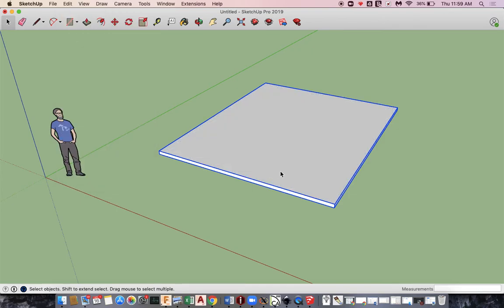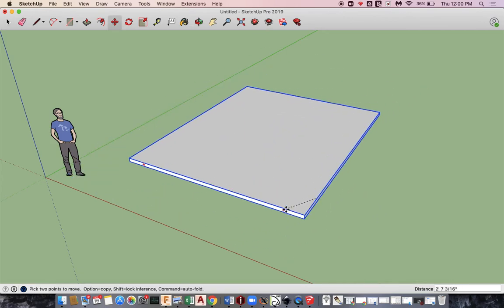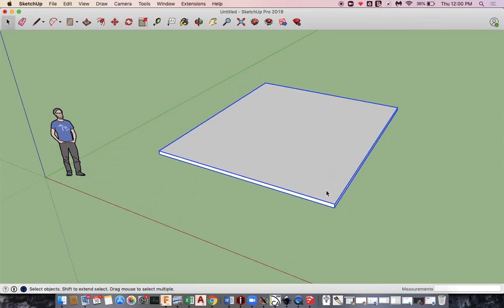Just hit Command G. Now, to tell that it's a group, it doesn't look any different when you're done, but when you select it, just click on it once. Notice everything is now highlighted with this blue border, which shows it's grouped together. Whereas before, when we clicked on it, it would only pick one face at a time. So when you have it grouped, you can tell everything is all together, and if we try to move it, it stays all connected, the right size and shape.